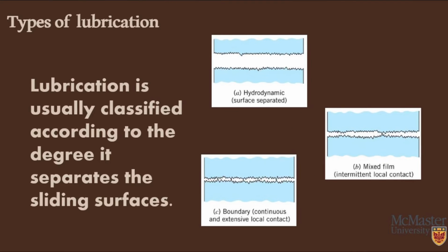There are three types of lubrication. Figure A shows the loaded journal bearing at rest. The bearing clearance is full of oil, but the load has squeezed out the oil film at the bottom. Slow clockwise rotation of the shaft will cause it to roll to the right, as shown in image B. Continuous slow rotation will cause the shaft to remain in this position.